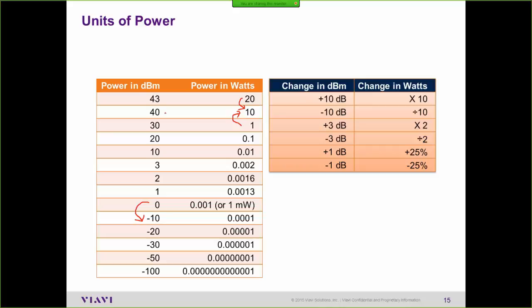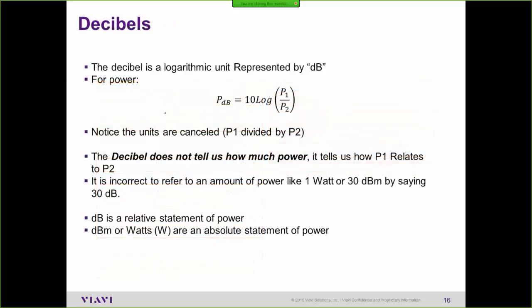All right, let's talk about the analyzer specifically. I said right at the beginning that a spectrum analyzer is nothing more than a fancy power meter. All a swept spectrum analyzer does is step across the screen and measure power sequentially in little tiny bins or buckets, whatever you want to call it. Every time it sweeps and steps up, it measures another power value.